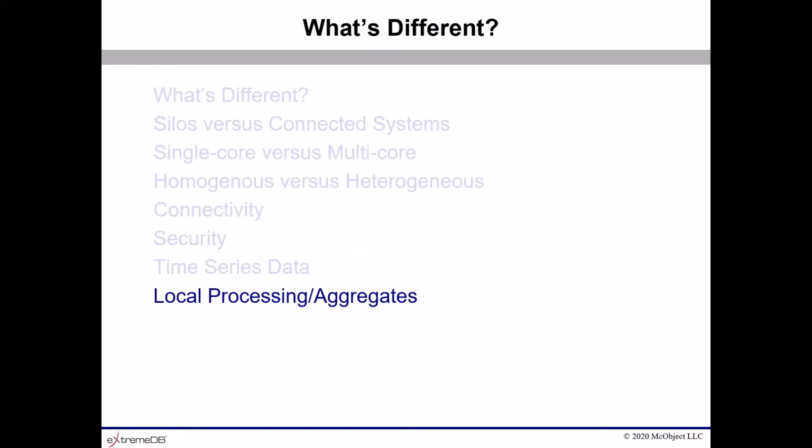IoT devices have the potential to generate a tremendous amount of highly granular data. Consider a sensor that samples data at 1,000 hertz. That's 86,400,000 elements every day. A device with 10 sensors, each producing a double precision floating point number, would generate nearly 7 gigabytes of data every 24 hours. 7 gigabytes.